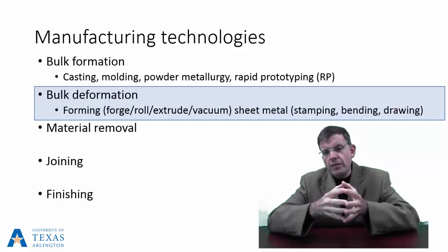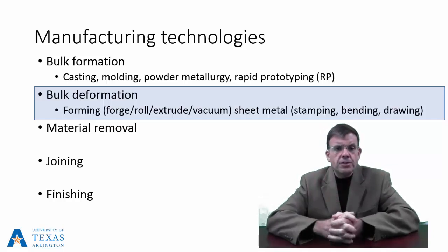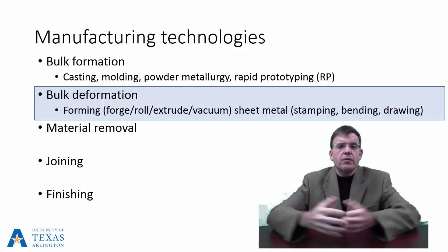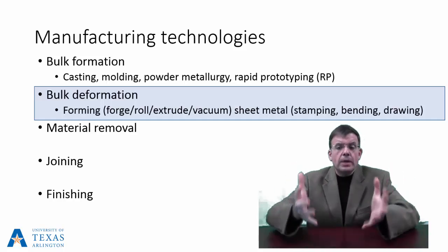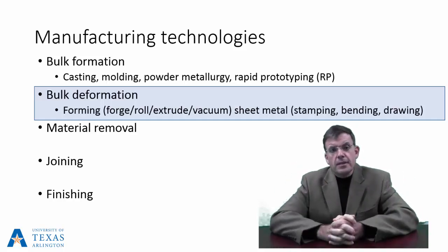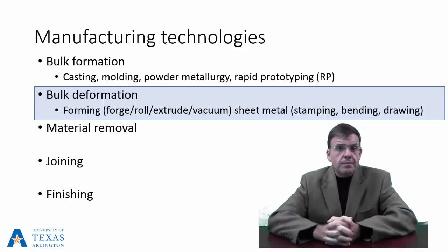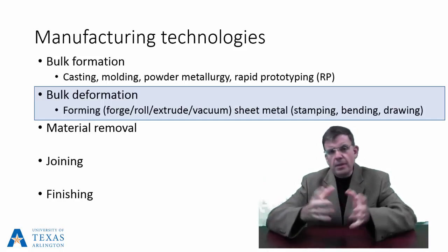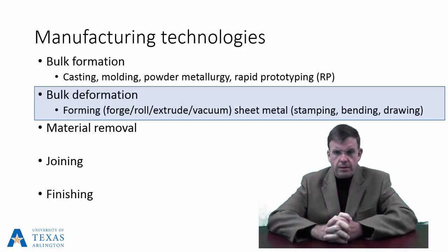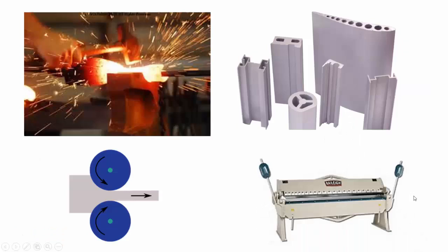Sheet metal turns out to have a tremendous range of applications. Just open any computer, and you are going to find that the innards inside the casing, anything that's holding the whole show together, is some manner of sheet metal that has been subjected to various processes, and these are unique to this particular category. I list them there: stamping, bending, drawing, but there are very many others, again, with their own particular lingo. Okay, all right.